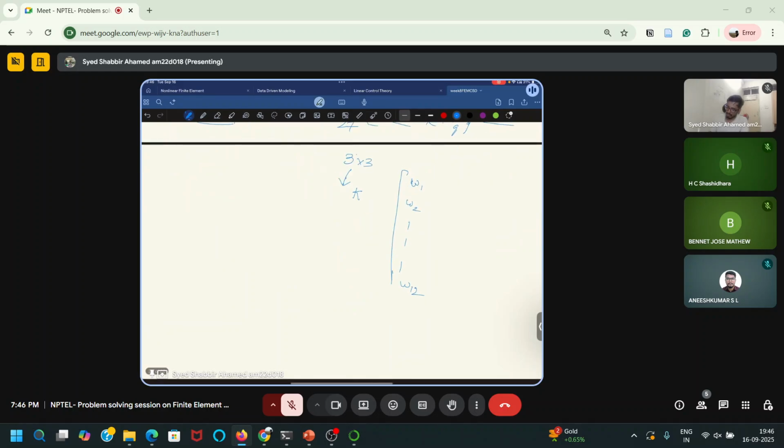I'm just assuming that this will have all slopes and displacements at each node. So you will have 27, right? So whatever displacements are becoming zero, you can just remove those equations. Okay, that is called static condensation.